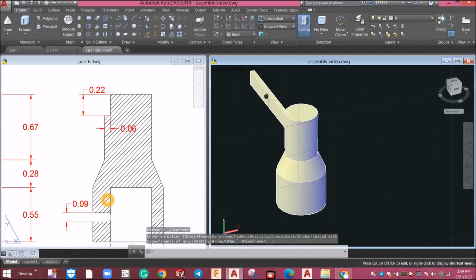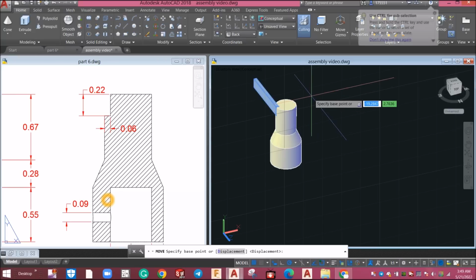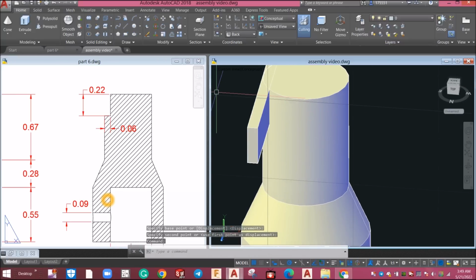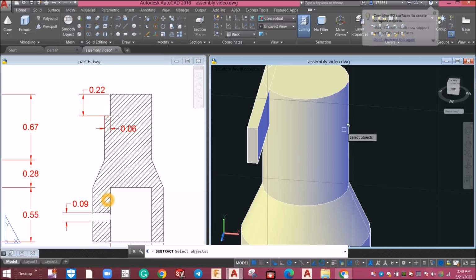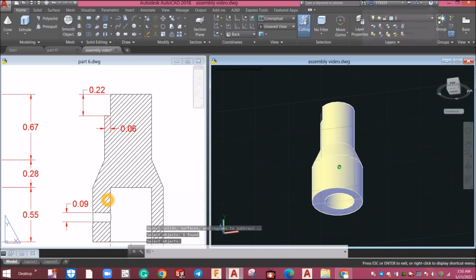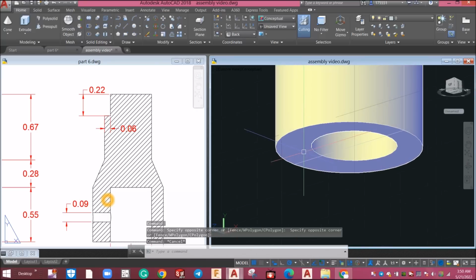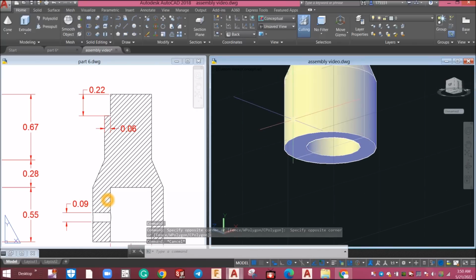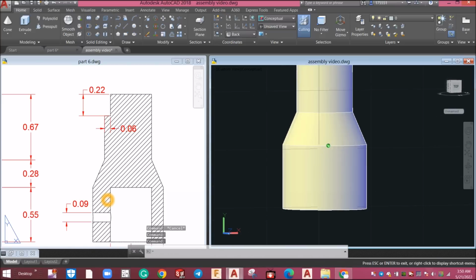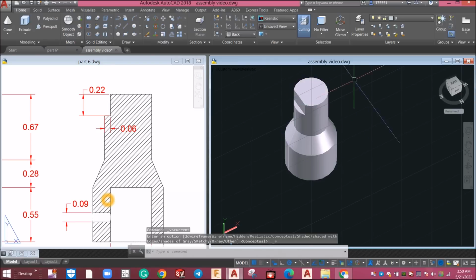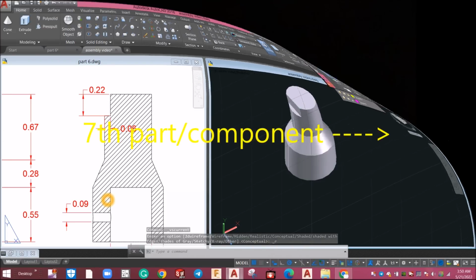I'm just gonna use conceptual. So I'm gonna move this one towards the center, so move along the z-axis vector. I'm gonna use this one to subtract. So inside the solid editing panel, select subtract command, select the object you want to keep, right click and select the object you want to remove. Yeah, I'm just making sure we are on. So this one has the biggest gap, which is this one here, and we chip off from this face here, from this direction. All right, so I'm just gonna change this to realistic and change the color to yellow.